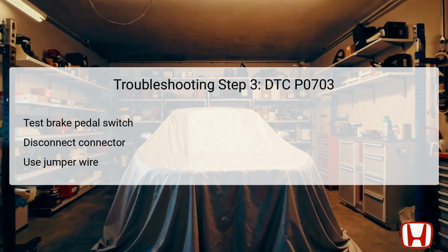This testing helps identify whether the brake pedal position switch or other components may be faulty. If the readings align with the expected thresholds, it indicates the switch requires replacement, while any mismatches prompt further steps, leading you to Step 4.